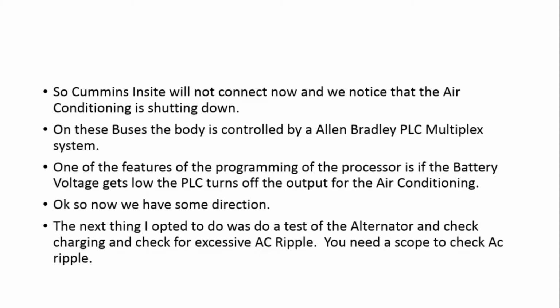It does that by monitoring an RPM signal off the back of the alternator. The bus computer is looking for half of the output charging voltage. So if you're putting out 27.3 volts, then it should be half of that, so around 13.5, 13.6.